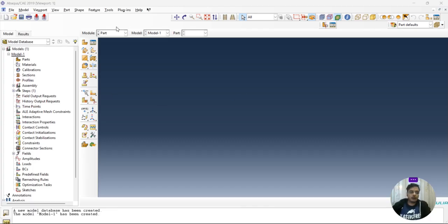Whenever we talk about Abaqus, one of the things that we have to understand is how we have to model it. So we have to go with this particular pipeline, where we initially start with the part, then assign the property, assembly, that we say instances, step, where we apply the loading step condition. Then here we define the load, define the mesh, and that's it, and run the analysis.